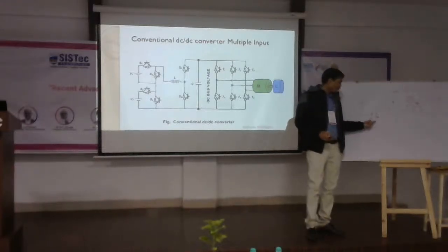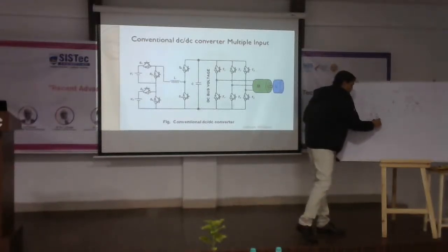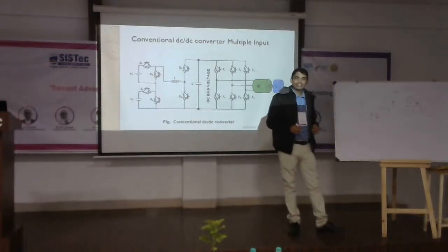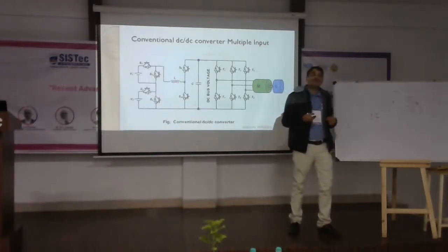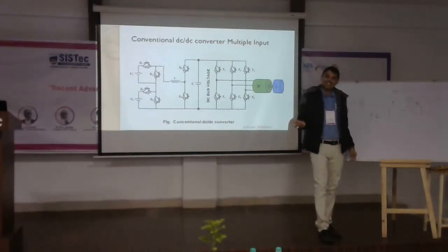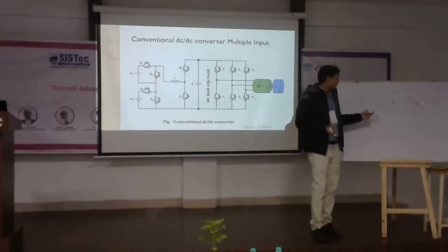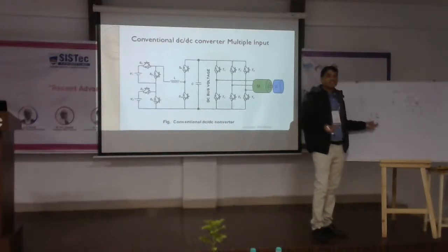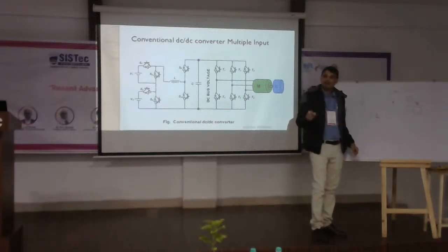Okay, and we want to vary the speed. Suppose you want a fixed speed, so you can maintain a 50% duty cycle. Suppose at 10 volts the speed is 100 RPM. So at 5 volts that will be reduced to half, isn't it? So the speed will become half.